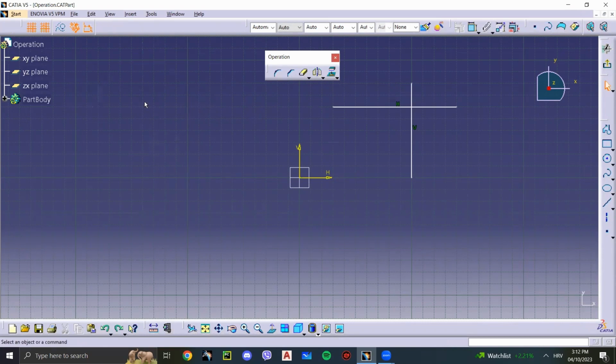Let's just remove that. You can double click it to keep on trimming, so you don't have to trim, then select trim. You can do it like this, and escape to unselect it. That's quick trim. An awesome command.